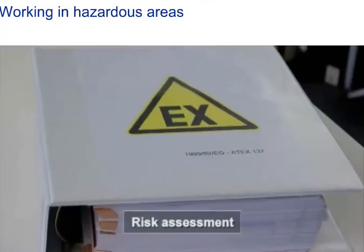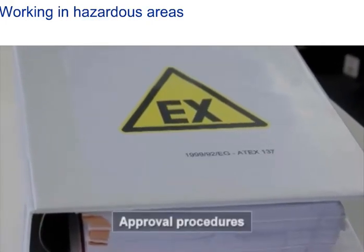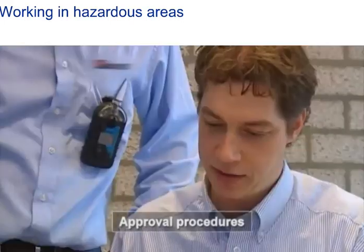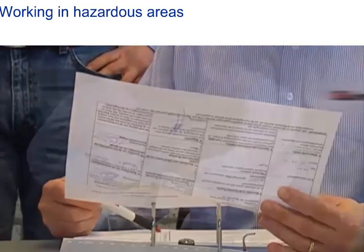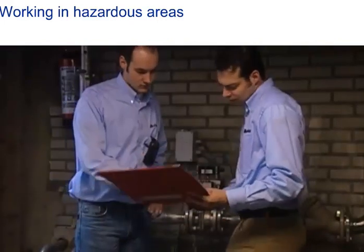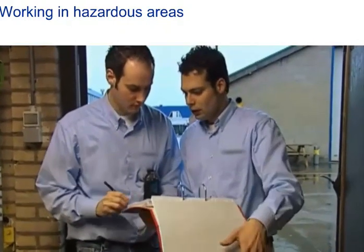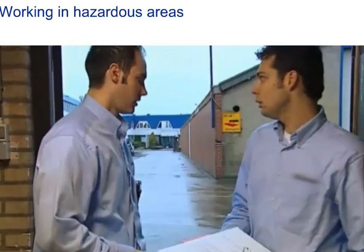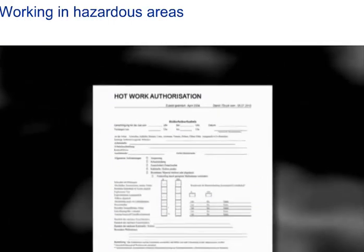The definition of the zones is an important part of the comprehensive risk assessment, which contains as well all the necessary protection measures. Approval procedures, as well as identification and security procedures, lockout, tagout, constitute important organizational measures. These set out in writing how hazardous operations in explosive areas are to be performed. You must never work without these approvals and must adhere strictly to the instructions they contain at all times.